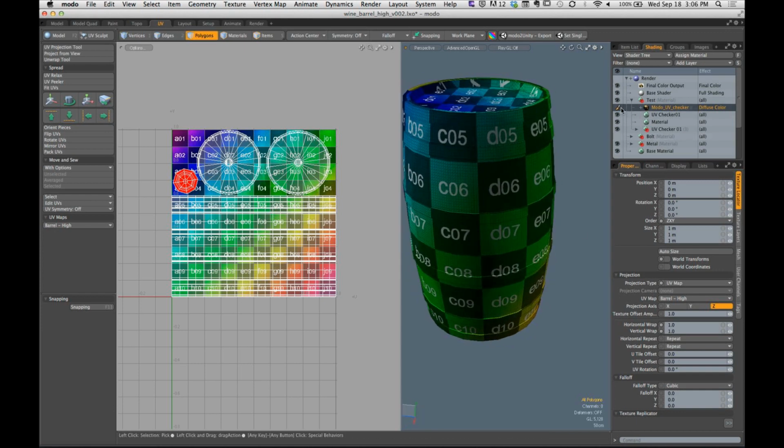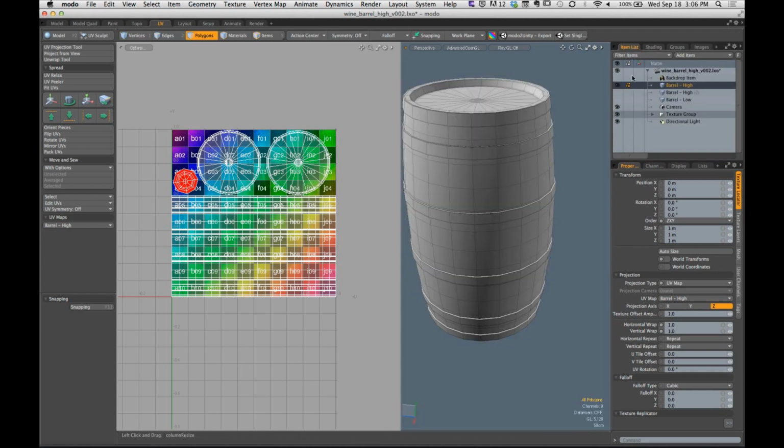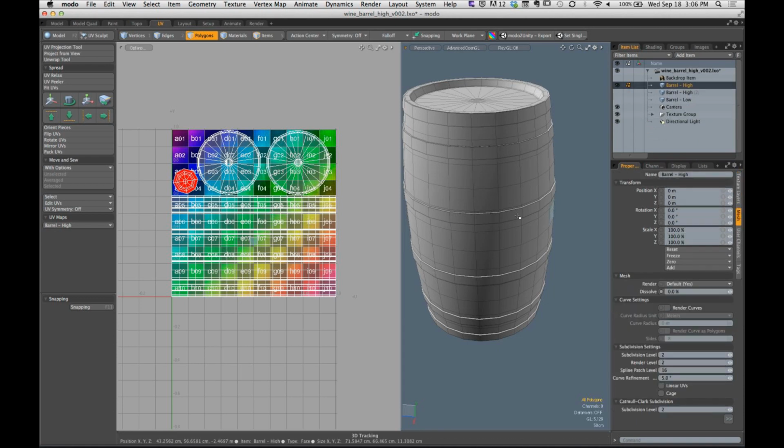All right, now that I have checked my object, I'm ready to get these UVs out of Modo and into Photoshop so I can create a custom diffuse texture map for this guy. So how do I do it? How do I get it out? Texture. Then where? Export UVs. Now, before we hit that Export UV button, let's triple check some important selections inside the application.